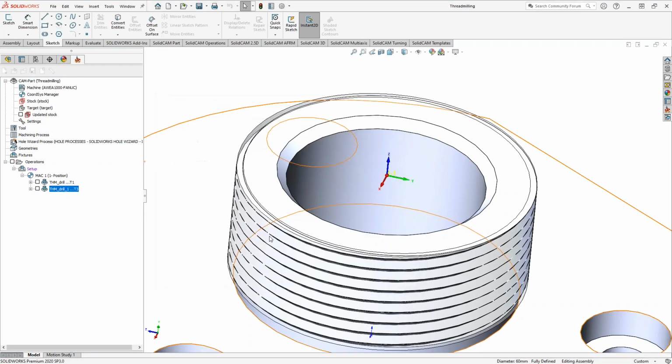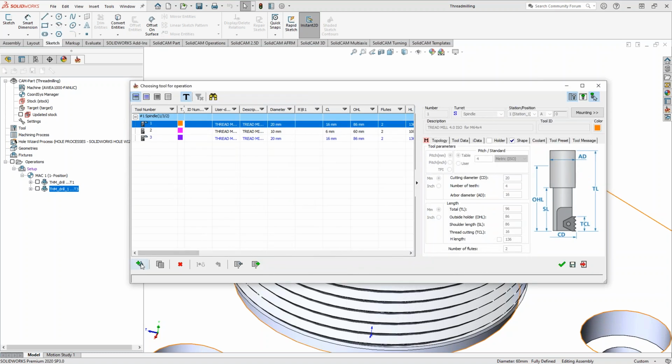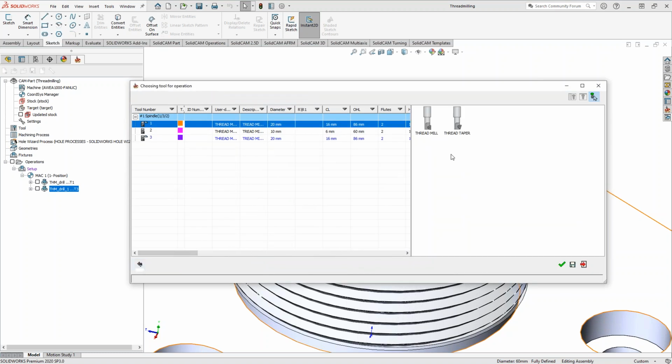The tool, well, this is one of those unique tool paths where when you click add tool, it really only gives you the one type of tool that's available for it. So you can't really do any thread milling with anything else other than a thread mill. Kind of makes sense, but there are other tool paths that we've seen where you might be doing something like a drilling and you could choose a flat end mill, or you could choose a lollipop or something.